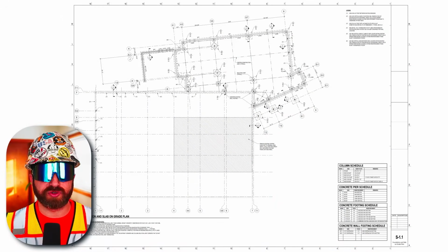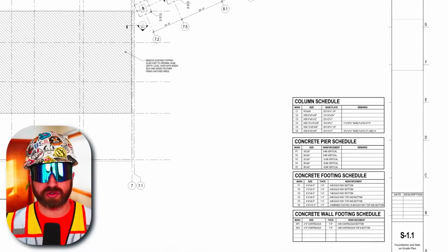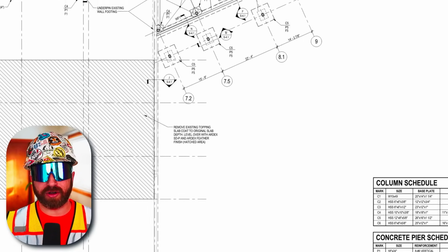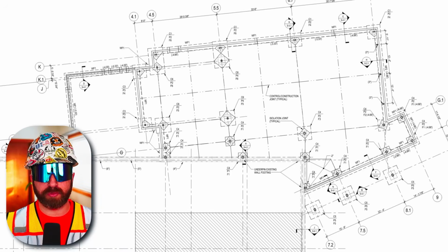Okay, let's jump into our set of drawings. So if you recall from my structural drawing review video, we actually reviewed this structural page S-1.1. On this page, we have a schedule that details the extent of reinforcement based on footings, walls, and piers. On a couple other pages in the structural drawing review set, we looked at more in-depth details that our rebar shop drawing designer will also capture. So again, the rebar designer took this baseline information from the structural construction documents and drew a set of shop drawings, which I have here.